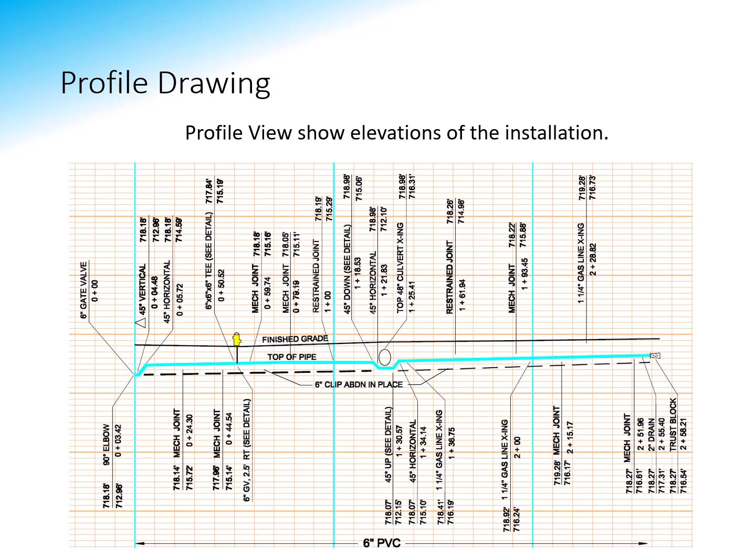Here you've got the profile view. So basically, like I said, you've cut away that piece of the earth, and so now you can see your system here, right? So as that main comes, here's that fire hydrant that was pointed out. Here's that end cap, and here's that storm drain crossing. And you can see that, whereas on the plan view it was a straight line, now you can see that nope, you've got angle points in here that are called out. And in addition to that, you've got those same stationings for the service laterals on this one, but you can see that both plans provide a clear picture.